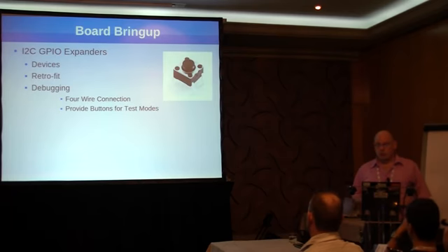One of the things that we use on a regular basis is a GPIO button. Normally the device will boot up in its existing modes as it would go out as a commercial product. But in some conditions I would like to have a test mode come up into a shell prompt or go into a diagnostic mode. And what I can do is have a GPIO button connected, and when I hold that button down while I'm booting, it will initiate the debug mode or the shell prompt as it goes through. Once you're done, you can disconnect this, and it's the same as before for your commercial product.